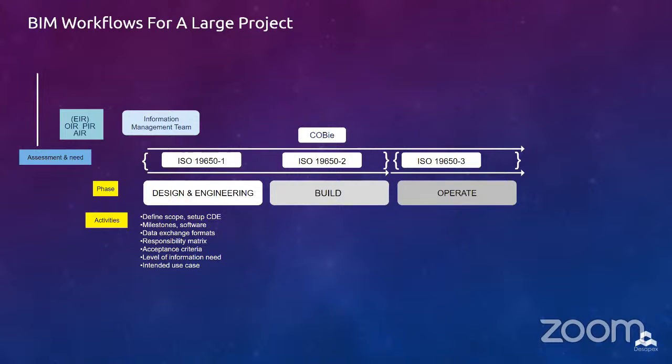Now, the next step would be to compile the technical system requirements, any special requirements, project timelines, EIR, the contract documents, anything else. All of this will be clubbed and compiled into an invitation to tender, which we also refer to as the RFP. It will be prepared for all the prospective architects, engineers, and other consultants to apply and respond to the EIR, which is the information management requirements, along with the other contractual requirements.